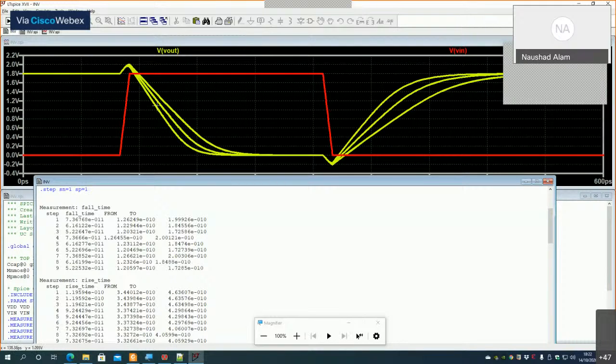Yes. It is because of the N MOSFET. Yes. So the P MOSFET is not playing a significant role here. So what are the 3 possibilities of the N MOSFET? The fast N MOSFET, typical N MOSFET, and slow N MOSFET.